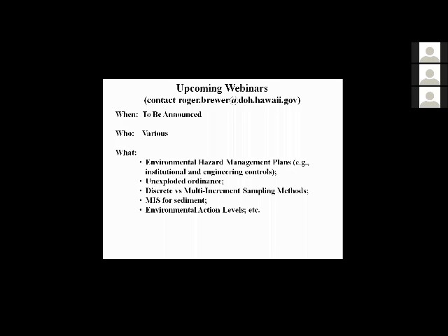But keep in mind, the purpose of the passive survey is to screen the site, to determine where you have contamination, whether it be in soil, groundwater, or even soil gas. If a risk assessment concern from vapor intrusion is the objective of the survey, that is the follow-on investigation to be required to determine what is the concentration that's present there, and to sample at different periods to see what is the average and high concentrations that might be present. So it's a separate objective. But reporting the data in units of mass, as a passive soil gas survey does, still meets the objectives of determining where you have contamination in both soil and groundwater and where you want to focus your remediation.